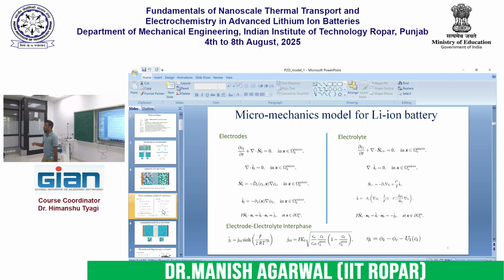In case of thermal field, we do use what is known as composite material. For example, you know that PCM, phase change material, has a lot of good energy storage capacity, but it is a poor conductor of heat. So a lot of the time we use what is known as a metal PCM composite. That means you have the metal along with the PCM, right? For example, you may have some kind of metallic fins, and in the other places you have the phase change material. So the material is actually a combination of the two, right?